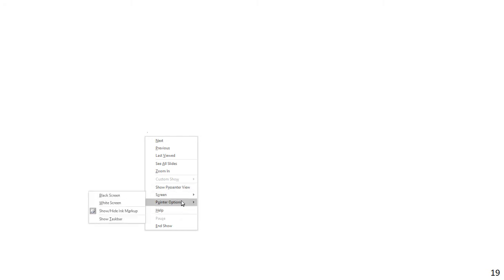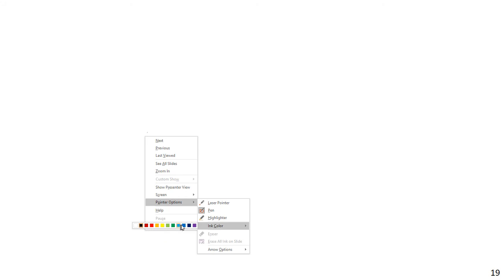And really this is what the concept of development length is. I kind of alluded to this earlier, but trying to predict the actual length needed for a given load is usually too much. So we don't operate on the principle of determining the actual load present and then making sure we have at least that much development length. Instead, we just design everything for the maximum. And the lengths are actually reasonable enough that this isn't a problem, so we can get away with this. But we need a way forward, and the way is like this.